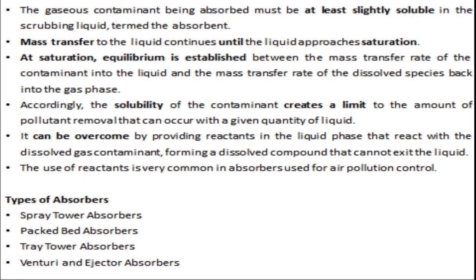This particular solubility limitation can be overcome by providing reactants in the liquid phase that react with the dissolved gas contaminants, and these dissolved compounds would remain arrested in that form and cannot leave the liquid easily. Then the final output would be good. The use of reactants is very common in absorbers used in this technology. So that gives you an overview of absorption as a technique.